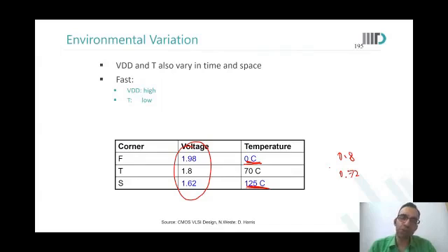However, when you're operating at low voltages, the total number of carriers that you have in the conduction band are not much. So when you increase the temperature, that carrier boost is much more than the scattering that would have happened because of lattice vibration and anything like that. And therefore, at low voltages, higher temperatures lead to better current.